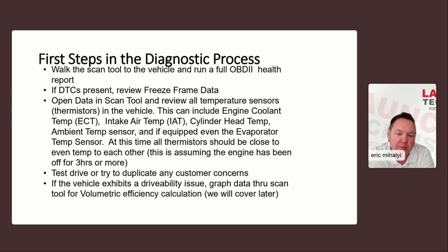If there is any kind of drivability issue, the first thing that I'll do is do a volumetric efficiency calculation with graphing data.